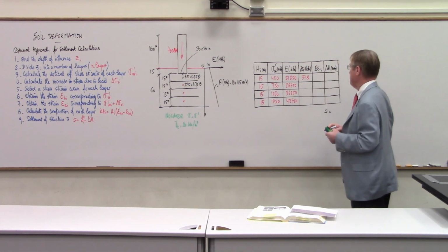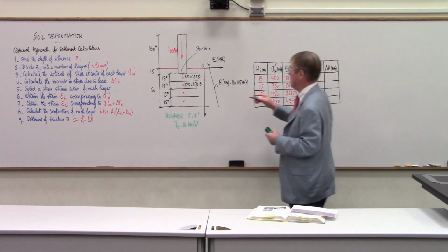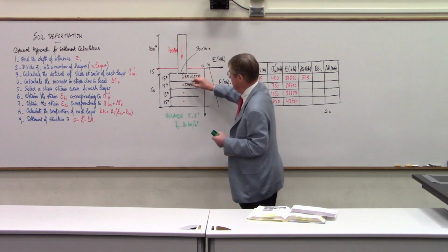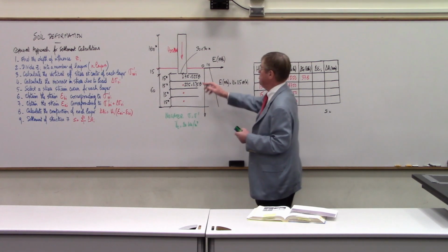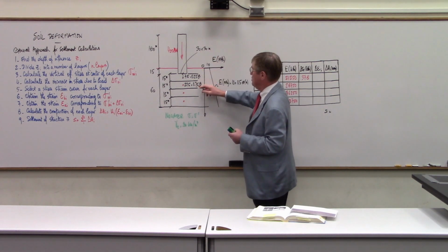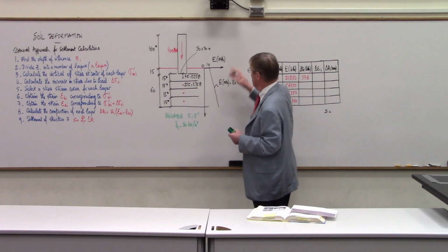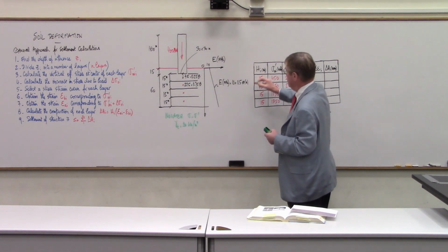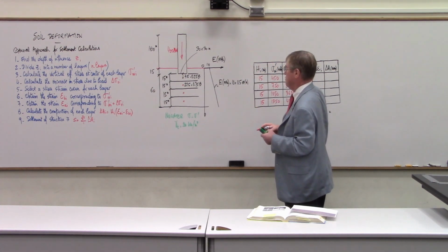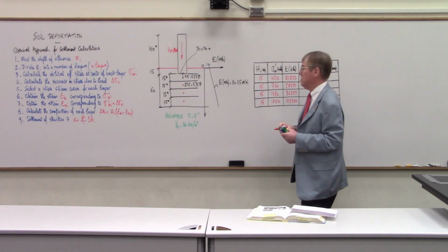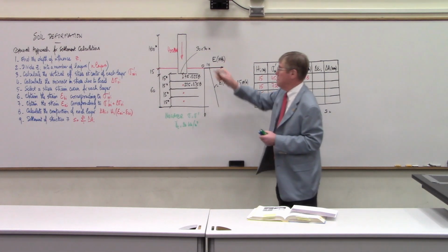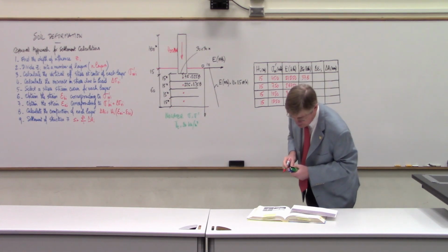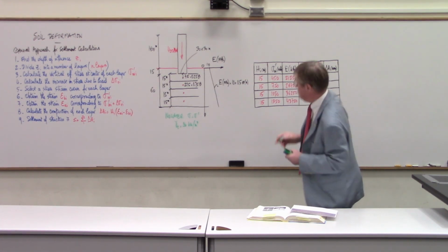Using the bulb pressure, I would then repeat the same thing, but now the depth below the foundation would be 15 plus 7.5, or 22.5, and 22.5 divided by 30 is 0.75 B. So on this left scale of the bulb pressure, I would go to 0.75 B, go right under the center of the square footing, and read the fraction of P, the pressure under the building, and times the pressure that gave me 222.